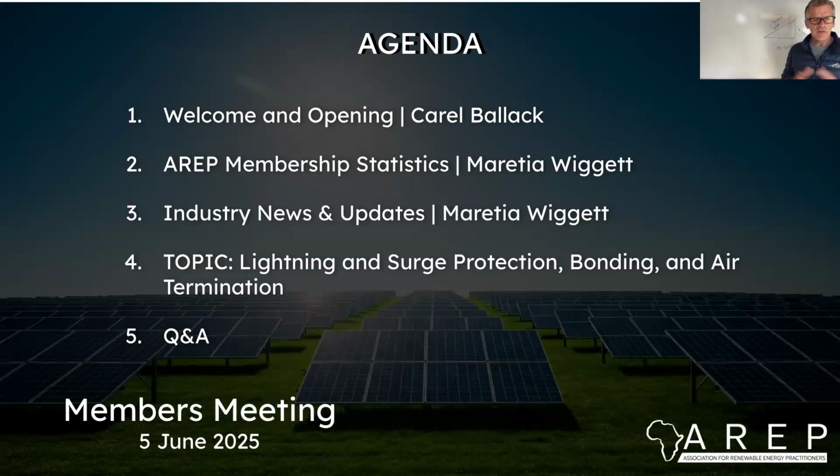There was an installation I went through to have a look at, and at the site, the guys had a load previously of 15 to 20 kilowatts. Their apparent power was 50 kVA, which mathematically means that the reactive power has to be 50 kVAR as well.